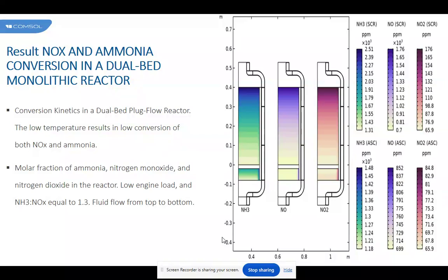Desirable properties of a catalytic converter include fast thermal response to give a short light-off time, which implies a low thermal mass. Thin wall monoliths generally have a lower bulk density and hence a lower thermal mass. Moreover, a low pressure drop is advantageous because it reduces fuel consumption. Pressure drop depends on both the OFA and the channel size, with larger channels giving a lower pressure drop.